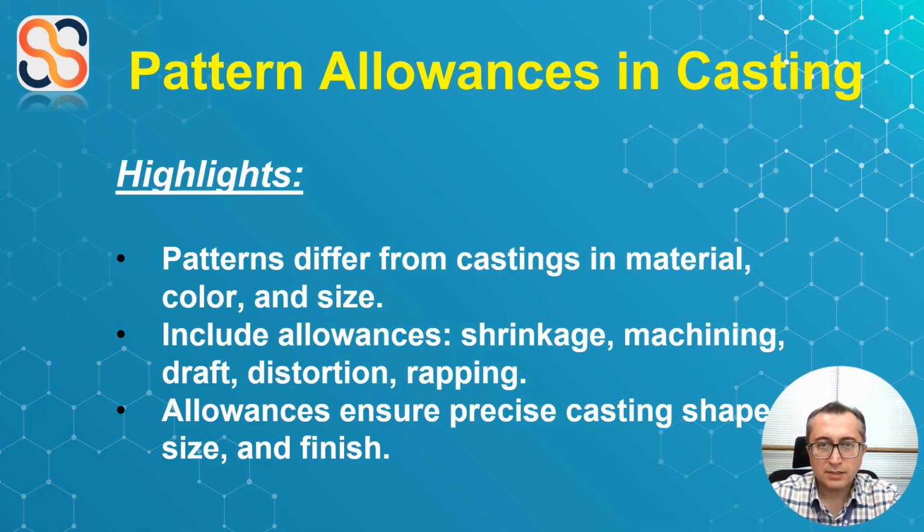Well, patterns play a critical role in the casting processes. They are crafted from wood, metal, or other materials, and often feature colors distinct from the final cast. This material choice is intentional, as the pattern doesn't necessarily need to match the casting material. It simply shapes the mold.